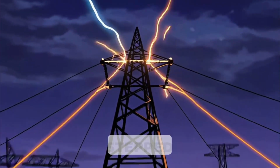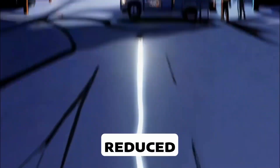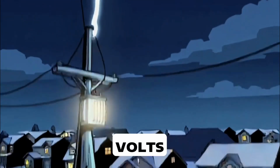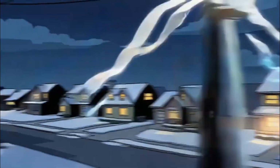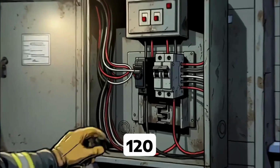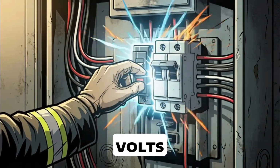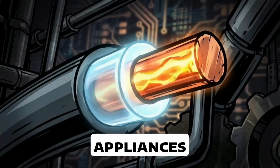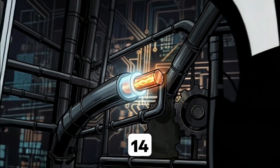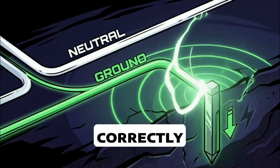Power is generated, stepped up to 120,000 to 220,000 volts, reduced to about 4,800 volts, then to 120/240 volts for homes. Single breaker equals 120 volts. Double pole breaker equals 240 volts. Some appliances need 20 or 30 amps. Gas appliances commonly use 15 amps on 14 AWG wire. Neutral is return path. Ground is safety path and must be bonded correctly.